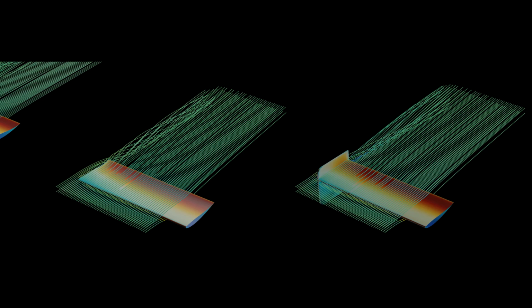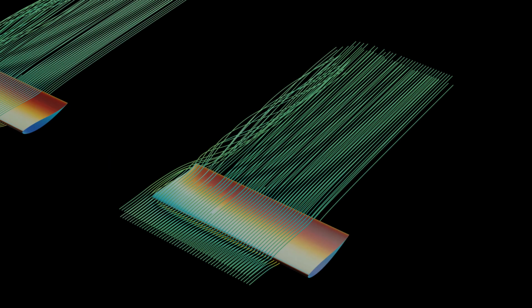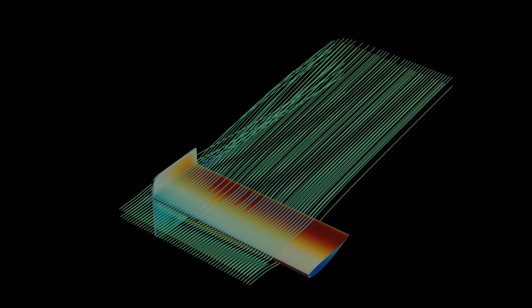Apparent from the 3D models, the vorticities are different with each endplate modification. Comparing the first and last, the vorticity difference becomes night and day. Without any endplate, there is a tight vortex that starts very early on in the chord. The larger endplate increases the radius, and the rotation appears to start much later.